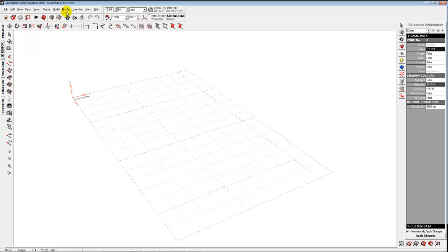What's most important though is how you model your assumptions and put them into the engine. So if you do a good job modeling your assumptions, it'll give you computationally very accurate results. But you have to make sure that the way things are put into the model are cohesive and properly attached. For example, one common thing a lot of people will do which gets you in trouble is if you take a very complex model in and you haven't optimized it, you haven't simplified it, or maybe you just have holes in your model.